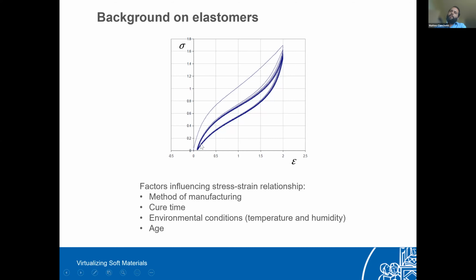There is, of course, first of all, some viscoelasticity that is very visible, and that is also leading to hysteresis, which is of course related to the velocity we are using in the testing conditions of the material. You can see that there is this first part of the curve that is quite different from the rest of the test, and we are going to see that in more detail why.